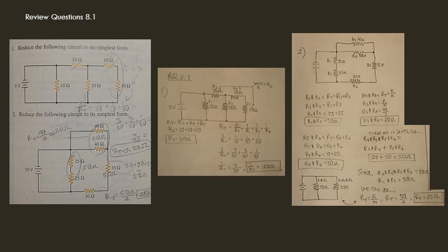So we can go ahead and find what that resistance is and combine it. More or less, you can look at it as combining those 3 resistors into one. That way we can simplify the circuit and make it a purely parallel circuit. So if we combine those 3 resistors that appear to be in series up on the top and on the right side,